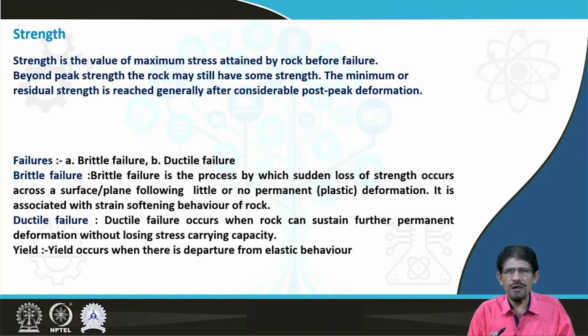This peak of the curve is not ultimate failure. Still, there is some strength present in rock, and this minimum value of the strength present in rock we recognize as residual strength or remnant strength.